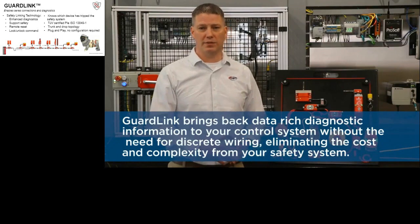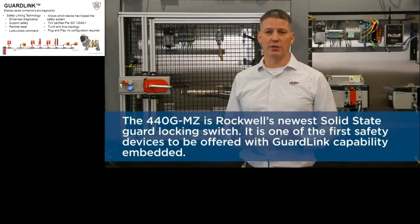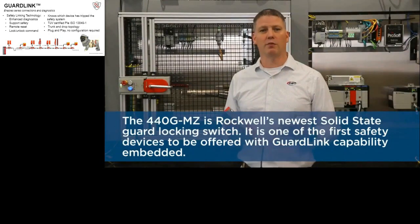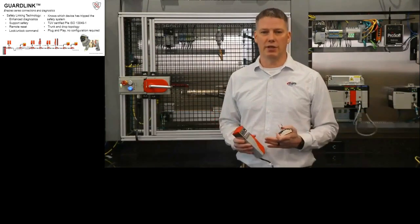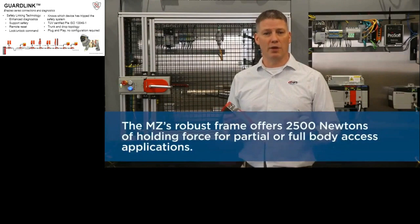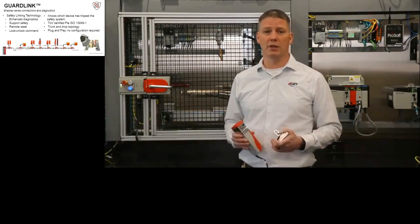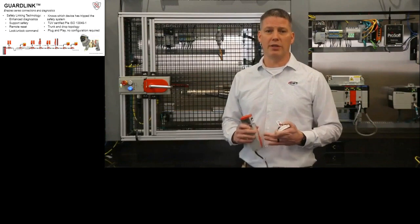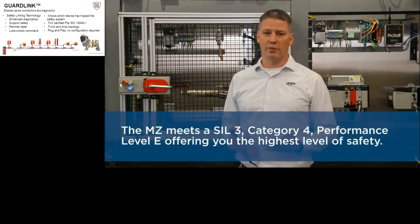The 440G MZ is Rockwell's newest solid-state guard locking switch. It's one of the first safety devices to be offered with GuardLink capability embedded. Simply put, it can be easily integrated into the GuardLink safety system. Available in power to lock and power to release, the MZ's robust frame offers 2,500 newtons of holding force for partial or full body access. With an RFID built directly into the actuator and OSSD outputs, the MZ meets SIL 3, Category 4, Performance Level E, offering you the highest level of safety.